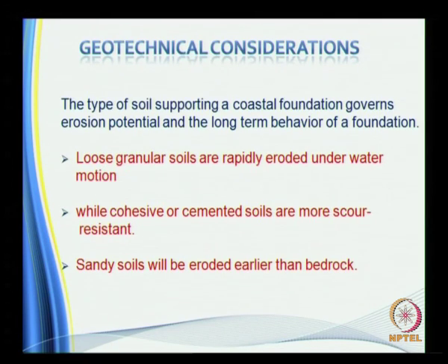Sandy soils will be eroded earlier, not only earlier, they will be eroded more rapidly also, compared to the other types of soil like bedrock, etc. So with sandy beaches, in case you want to promote some kind of infrastructural facilities on a sandy beach, then you better be on the watch out for the scour.